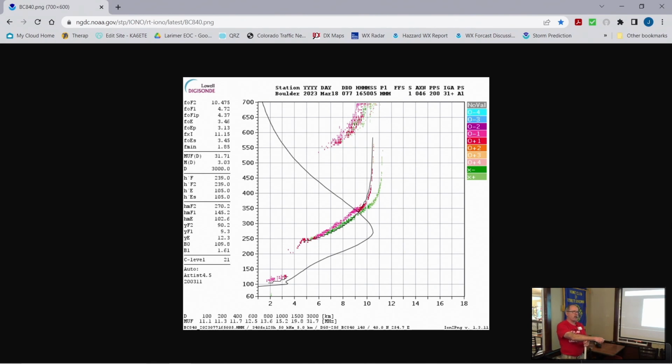General rule of thumb, if you don't have access to this, say you're out in the canyons or in the mountains and you have a problem, and you can't hit a repeater, and you want to try NVIS, and you don't have internet access to pull the stuff up, the general rule of thumb is 80 meters at night, 40 in the day, and 60 in between those. That's the general rule of thumb if you have nothing to look at. Set up and start listening.